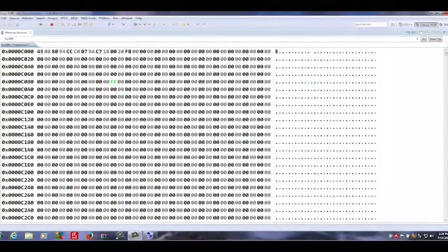If we push in an FF here, remember when it's green it hasn't changed until we hit the enter key. Look at that, it allows us to change what it thinks is simulated flash. Also, if we take a look up here and we change this to say 0, 0 or something different, notice it takes. So there's a big difference, as you'll see, between real flash and simulated flash. And it asks you what is the difference, and basically the difference is that in real flash it's a default of FF and you cannot change it with the memory browser. Now this is on page 4. In simulated flash the default tends to be 0, 0 and you can change it to any value you like.